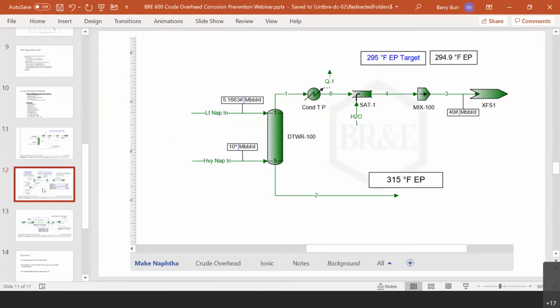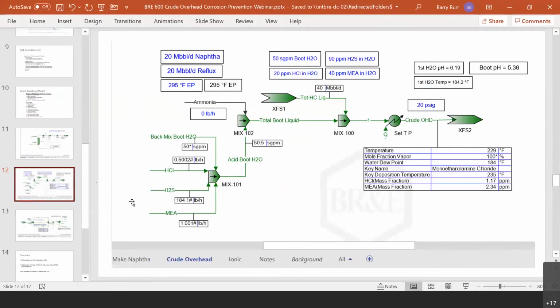The next flow sheet is where we prepare the overhead vapor stream, the combined overhead vapor stream. All these blue text fields are fields where you just click once, type the number that represents your plant measurement, and hit enter, and that loads that value into the corresponding property inside of ProMax. So you never really even have to go into the project viewer for ProMax in order to configure this model.